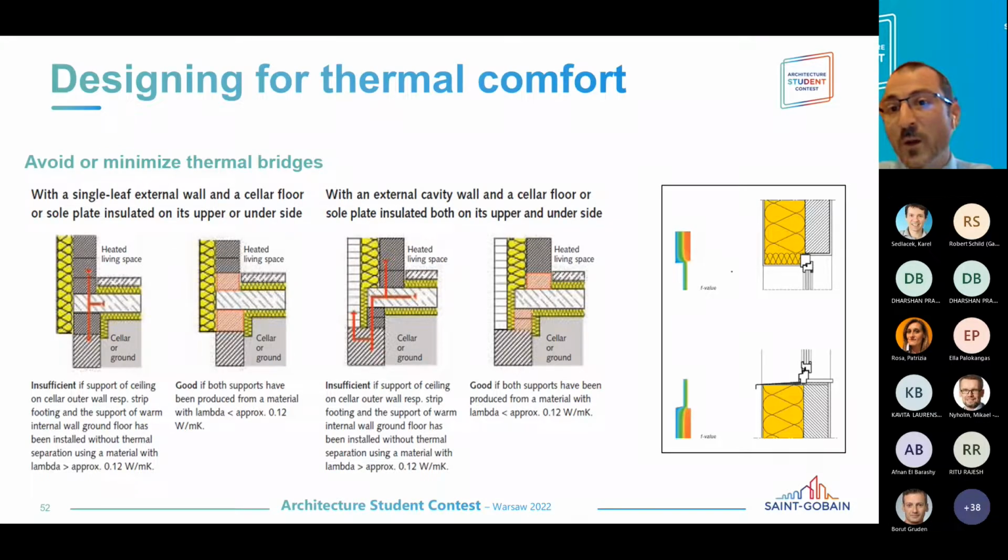And then you have here a detail on how you can make this detail. You can see it here. Basically, the insulation is covering the frame of the windows, which is already insulated, and this way you ensure that there is no thermal bridge in the area of the windows. If you remember the first image, the thermal scan that I was showing to you, in case of windows you can always find this if the detail is not solved correctly. So this is one point where looking a little bit at the details can make a difference, and can give the design a value of, okay, I've been thinking about how I can solve this.